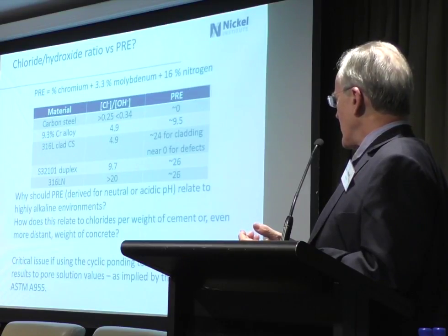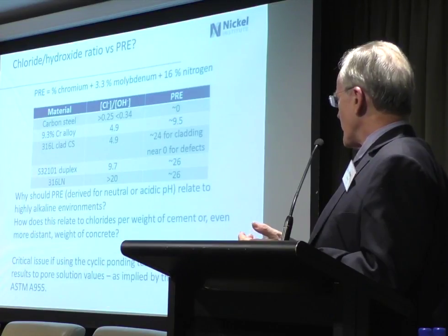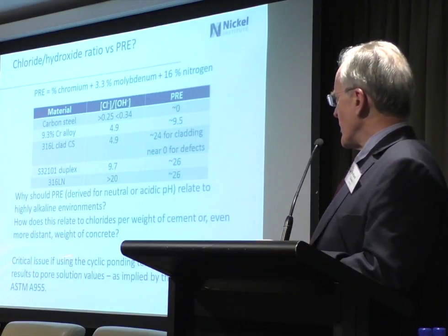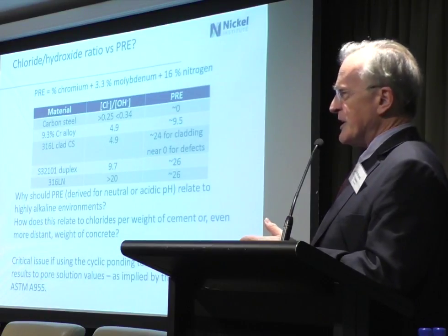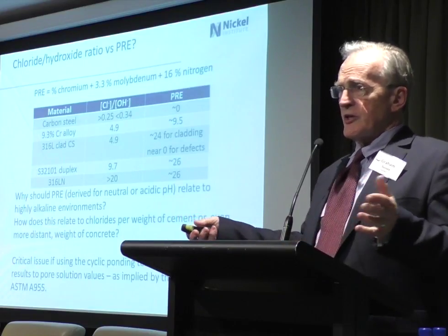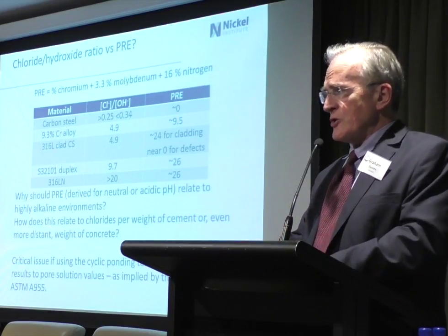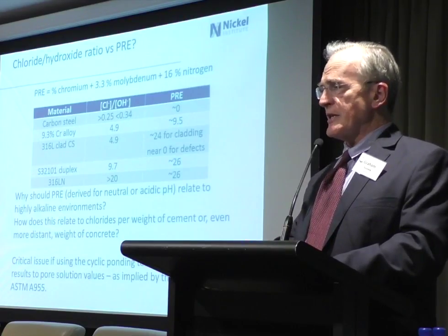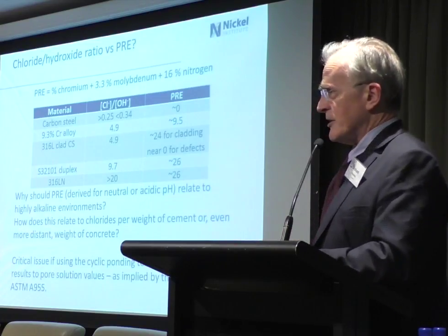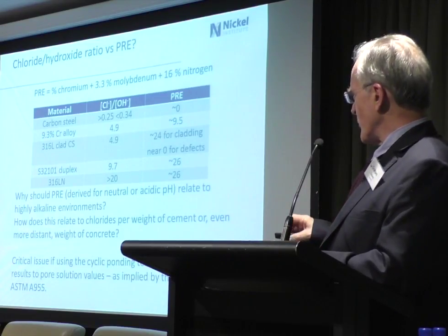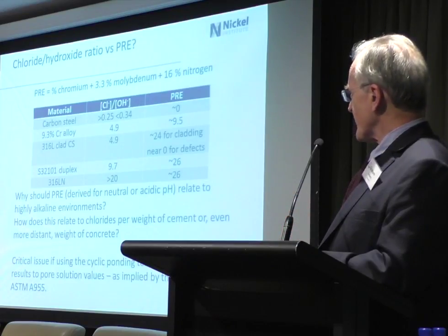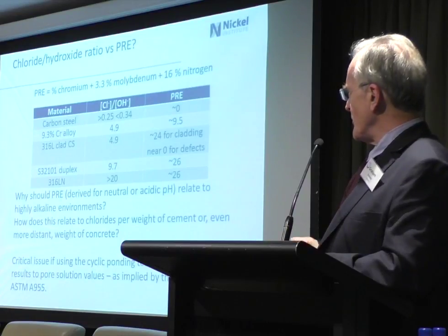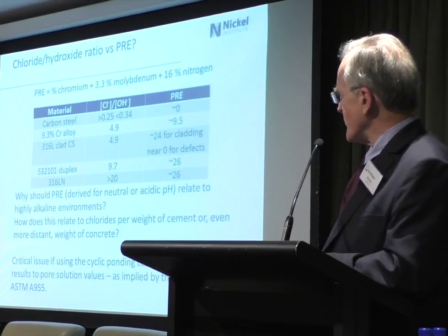I'm not going to deal with that. It's part of the argument about when you're using a cyclic ponding test and you're first feeding the solution in. There's a standardised test, you're meant to use the same solution, but you really don't want the thing to be more than damp, otherwise you suck stuff in and your initial surface concentration of chlorides distorts the whole test. Let's not get into that. There are people here who've done the tests themselves and know very well the precautions you've got to take to do those tests.